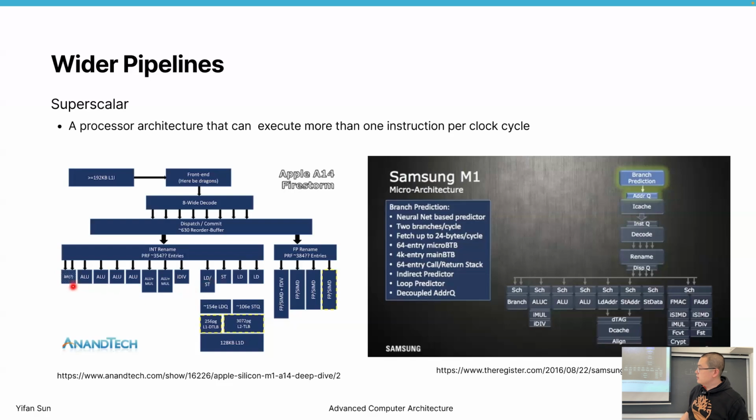So what they do is say this one is a branch instruction, right? It only takes care of branch instructions. Then you have ALUs. By the way, these are integer parts. These are floating point parts. These are integer ALUs, and we only have one division unit, dedicated to division operations. It takes a rather large die size, and only these two can calculate multiplication. These are probably adders or shifters. 4 of them can take care of load store unit, and 4 of them can calculate floating point operations. So this is the design.